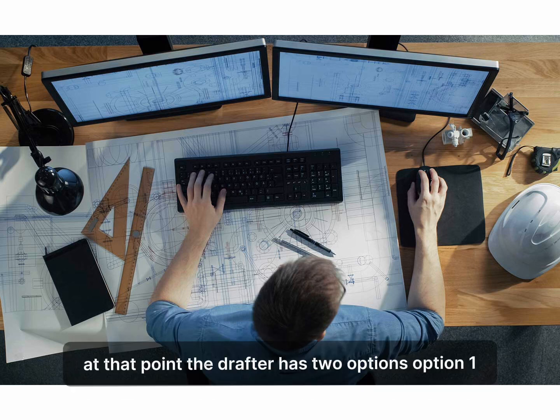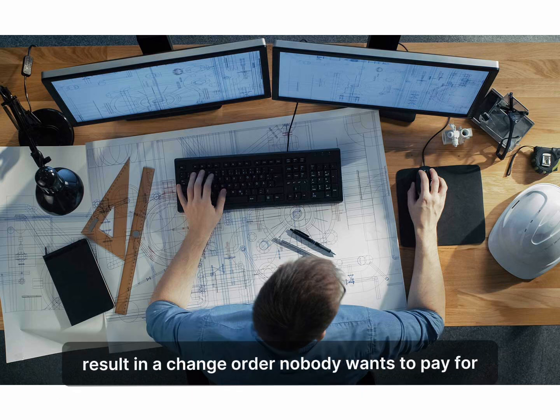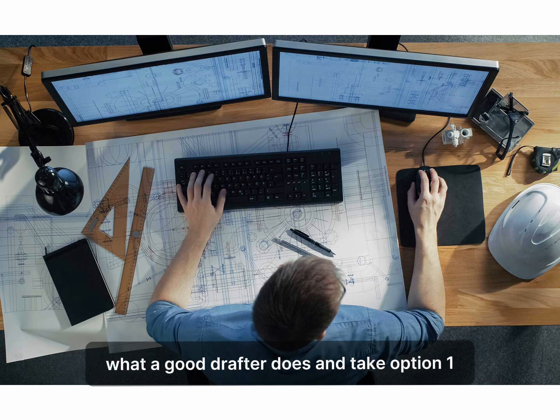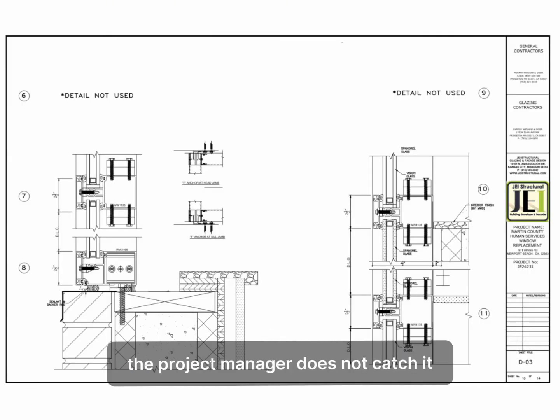At that point, the drafter has two options. Option 1, tell the project manager, flag the missing embeds, and wait for an answer that could take 3 weeks and might result in a change order nobody wants to pay for. Option 2, draw the system as a window wall, bearing on the slab edge, because the slab edge is right there and it works structurally. What a good drafter does is take option 1. In this case, the drafter takes option 2. It keeps the job moving. The project manager does not catch it.